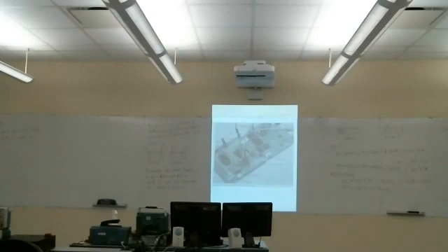So through the use of the selection registers, we've designated various pins as being I/O pins as opposed to analog to digital converter or serial interface pins. But once we've done that, we still have to choose whether we want to be able to write to that pin to turn an LED on or off, or be able to read from that pin, like reading in from a switch. Now, we only need to set one bit for that, and that's done through this direction register. With a 0 there, I think it's an input. With a 1, it's an output. We can write values to that.